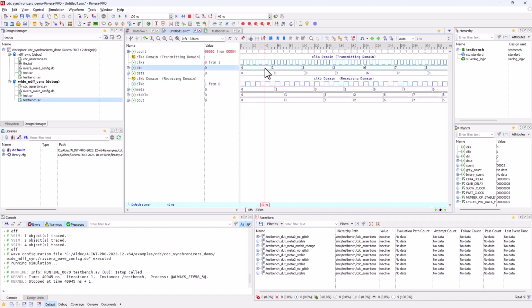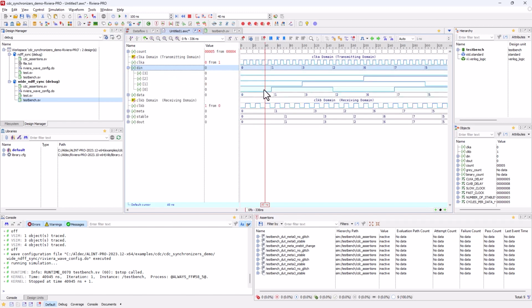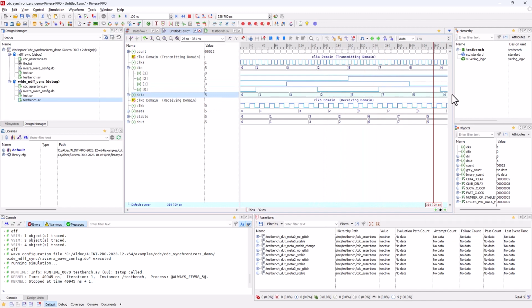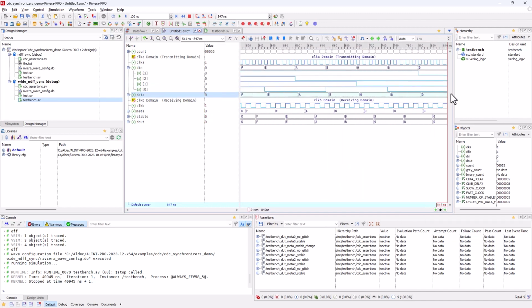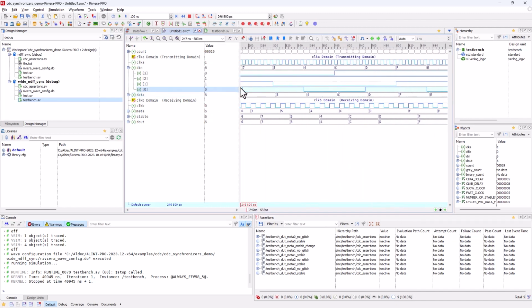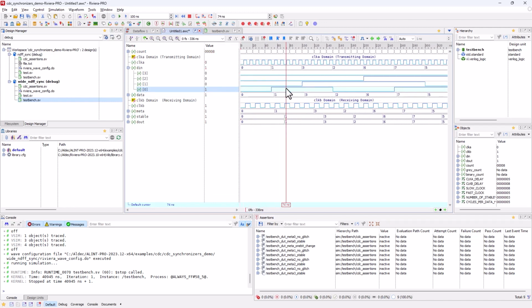And so the next thing we want to check is the stability in terms of one bit being changed per cycle. And so we'll notice that, again, because we encoded this as a gray code counter, every single one of these changes only manipulates 1 bit. So here we change the bottom bit, here we change bit 1, bit 0, bit 2, and then we change bit 0 again, and so on. So we never change multiple bits simultaneously. And so this preserves, or rather allows, the assertion to not be violated.